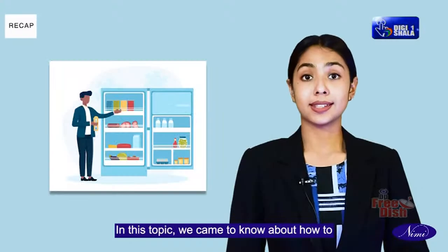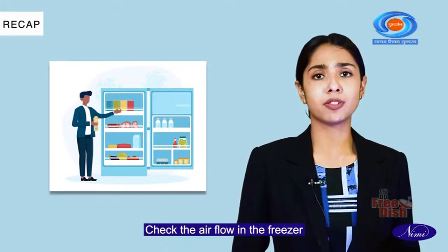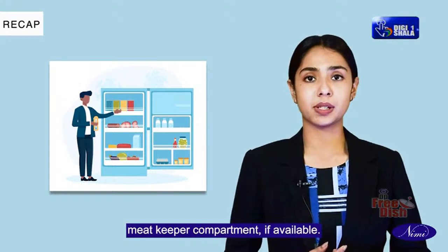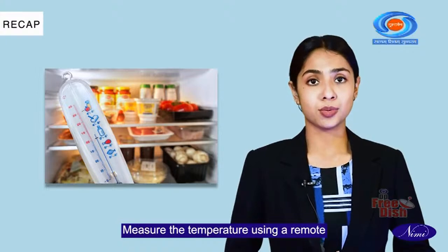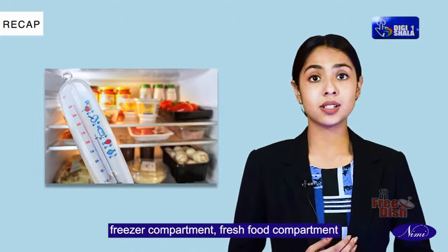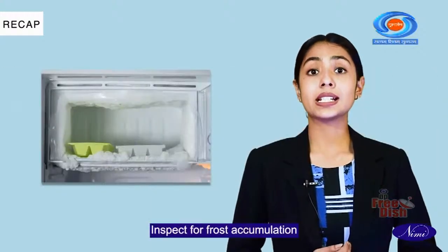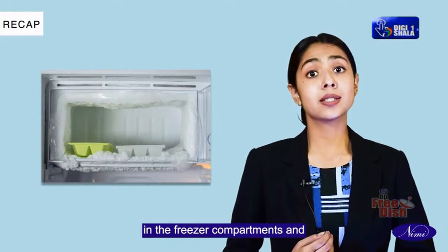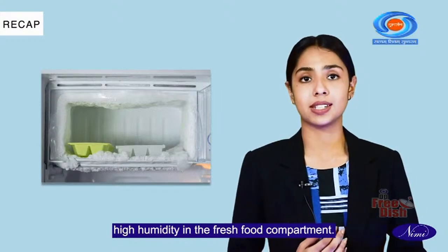Recap. In this topic, we came to know about how to check the airflow in the freezer compartment, fresh food compartment, and meat keeper compartment if available. Measure the temperature using a remote sensing bulb thermometer in the freezer compartment, fresh food compartment, and meat keeper compartment. Inspect for frost accumulation in the freezer compartments and meat keeper section, along with observing high humidity in the fresh food compartment.